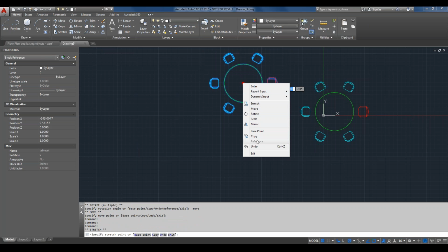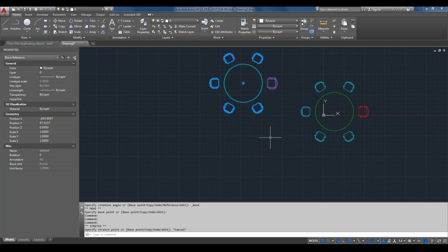And let's see, do you have to have the same unit set in each drawing in order to drop it to the same coordinates? Yeah, that's a good question there, huh? I would say that you would have to, because if you have an imperial drawing and a metric drawing and you just do copy and paste like that, it's not going to come in where you want it to. Yeah, and I agree with you, Dave.